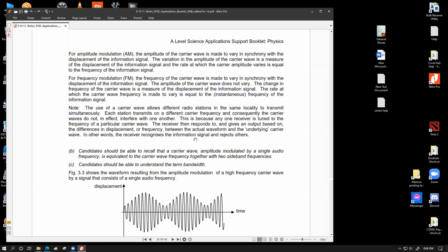Your cell phone has the capability to tune its antenna at any of this frequency value that the tower commands the phone to tune with. So the tower tells the telephone antenna that I want you to operate at this value. Your cell phone antenna operates at that frequency. Whenever you make a call, this call happens through the communication channel, through the telephone network. The moment you start to talk through your phone, you add your voice to that specific carrier signal frequency which was assigned to your phone from the tower, and they do the merge.